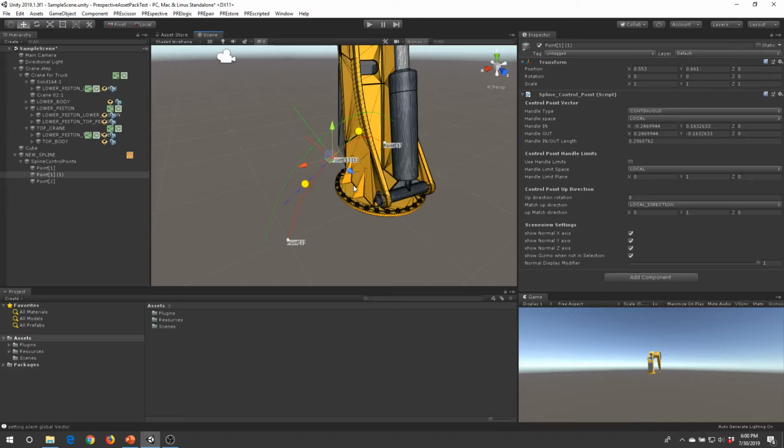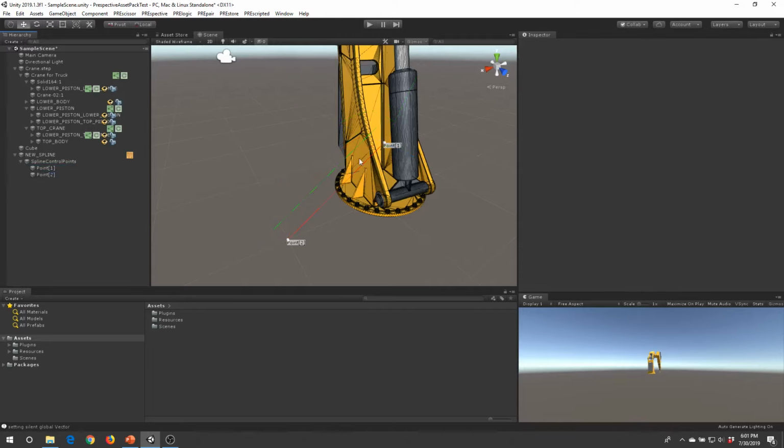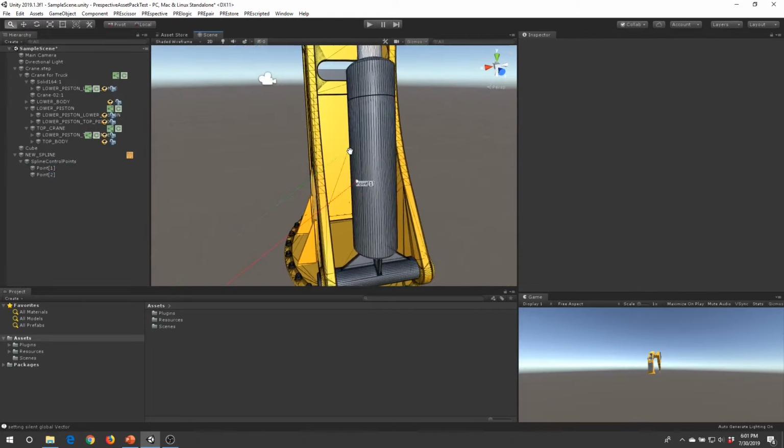In a future tutorial we'll also show you how to create a belt system, a moving belt system, and that makes use of a loft based on splines. So we'll show more complex spline functions in there, but for now we'll just use a spline consisting of 2 points. So I'm just going to delete this particular center point. We don't need it for our application.